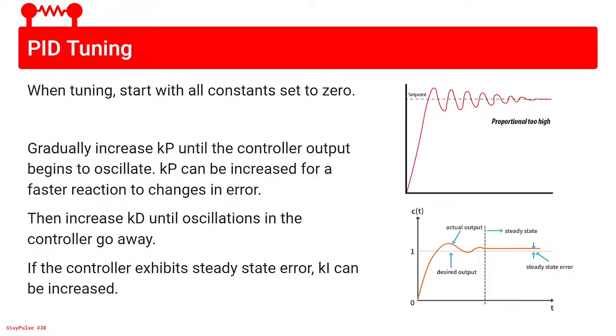Yes. It's not on the slides, but there is an equation. Sorry, not an equation. A routine that can automatically calculate these KP, KI, KD values, or even just P or just PD if you only want P or P and D. The routine is called a bang bang loop, where you run the system at 1 until it zooms past the target, and then at -1, or 100%, -100%. So it's going to oscillate around the target.